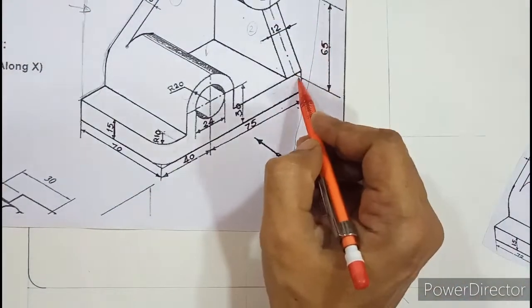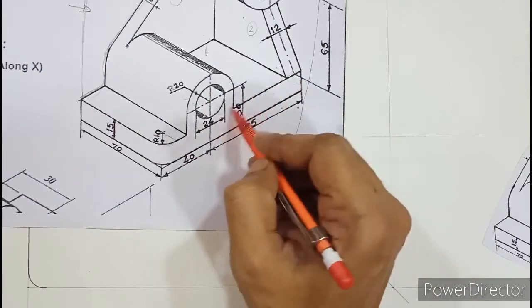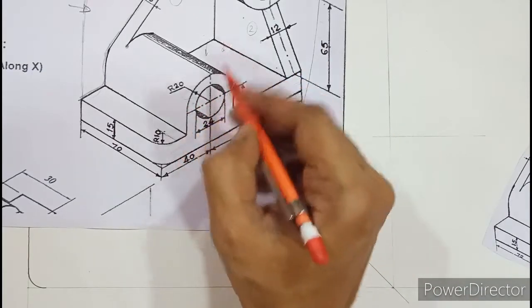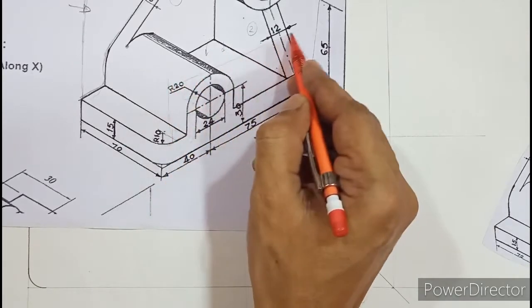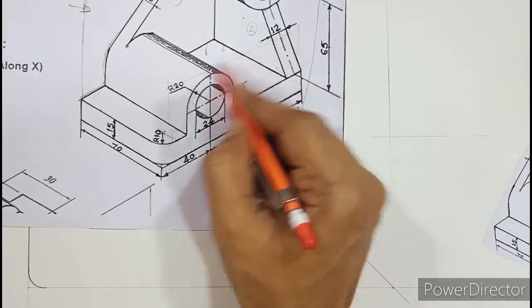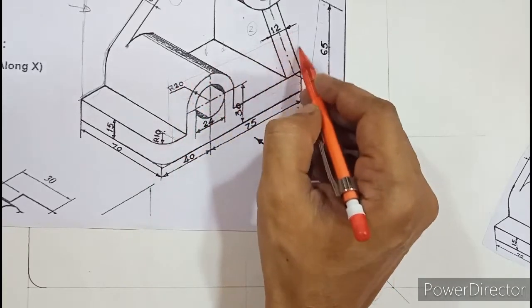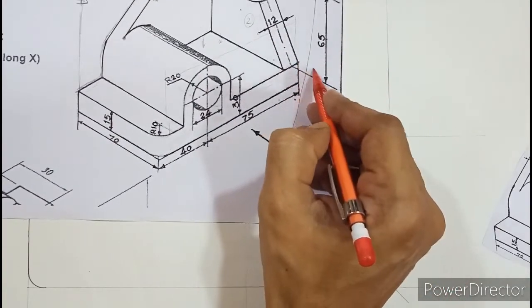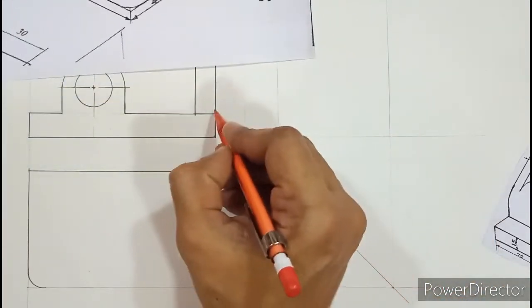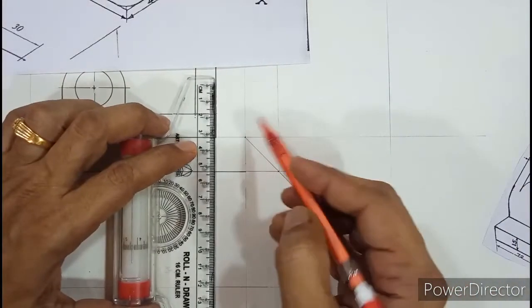So in the top view, this one single plane concept is seen as a line. So this complete vertical surface, in the top view, if you observe, it is seen. So let us project from here. So from here to here it is seen as a continuous line because this is one single plane. But this continuous line is not till the end of the box. It is till this point. And see this point in the front view, if you try to recognize, it is over here. Okay, so I need to project this point down.